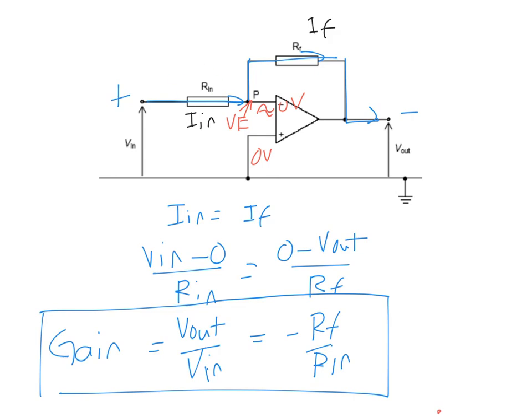So in that case, you get fixed whatever gain you want. And can you see there is greater operating stability? Because now your gain only depends on this. It doesn't bother about the condition of your op-amp inside there. Understand? Okay, so remember, if it's an inverting amplifier, you can only use this. Okay, so let's do some questions.